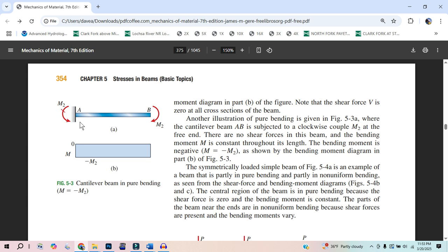This is where I show you, go back to your diagram, there is just air surrounding this beam from here to there, and then from here to here. So we can't have any magical forces just appear between A and B. The only place forces can exist is where we cut this at the wall. That's the definition of an internal force. Now, when we cut this at the wall, we're treating this as a reaction.